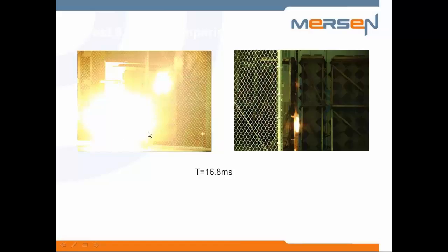And note that these gases are laden with copper oxides. You're vaporizing and actually ionizing copper off those electrodes, which are going into this plasma and expanding rapidly. So we're impregnating everything inside this equipment with copper. At 32 milliseconds, there's no remnants at all of the arc on the right, and this continues to expand.